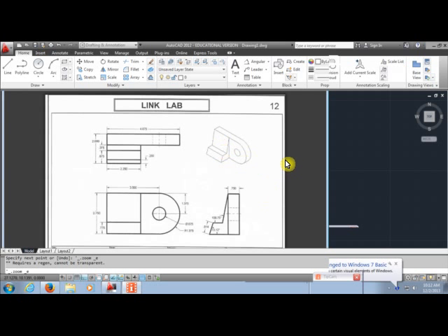Okay, so I need to drag down from this, and I need to make sure that I have my O-snap from midpoint on. And then I can drag down from here, and I can drag out from here, and where they meet should be where I draw the center of my object. But now what you're seeing is why you can't use those exactly in isometric. So I would have to come out from this at an angle that matches the other one.